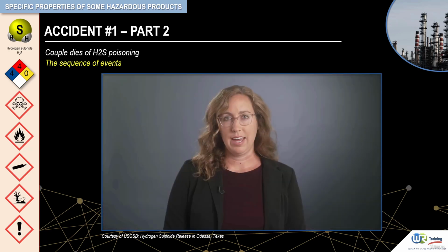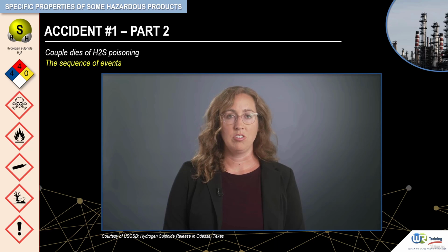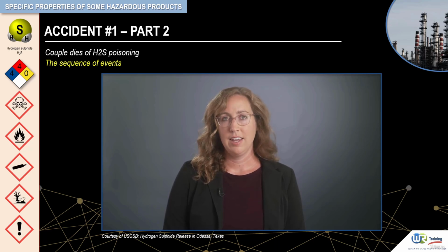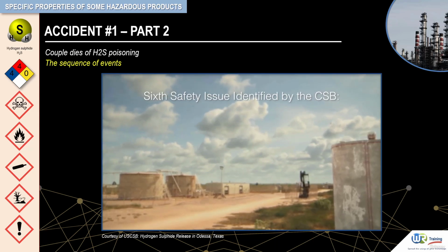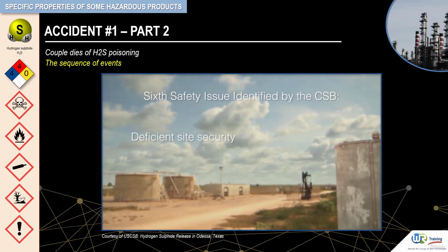At facilities that handle toxic gases, gas detection and alarm systems must be adequately designed, maintained, and tested. Alarms should clearly alert to the hazard through visual and audible indications. Visual indications should be discernible during any time of day. Signs alerting that the facility handles toxic gas should be posted in clear view, legible at day and night, and should be well maintained.